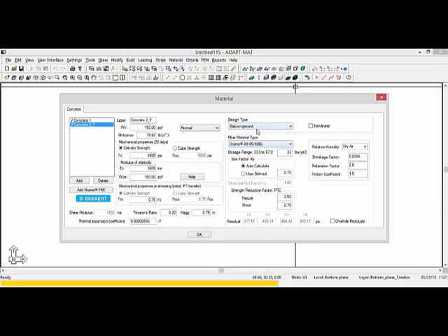And you'll notice that the program reports some residual stress values, FR1 through FR4, which are used to generate a model for the tensile stresses for these particular fiber types. These are the tensile stresses of the concrete at certain crack widths using the fiber type. If you want to override these values, you can select the option to override the residual values. The user can then come in here and modify these as needed.